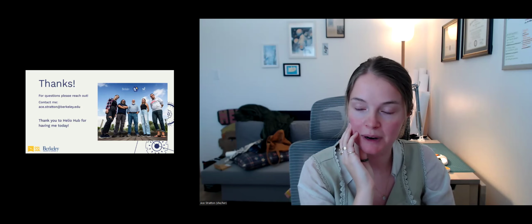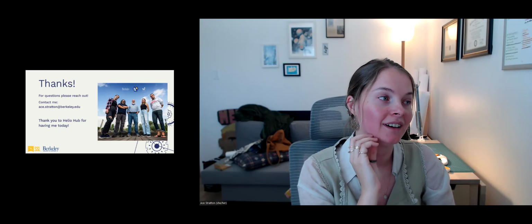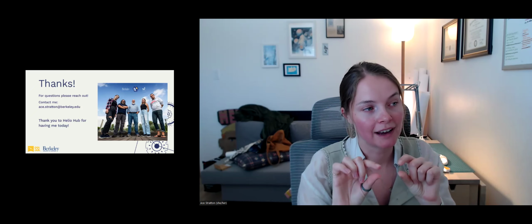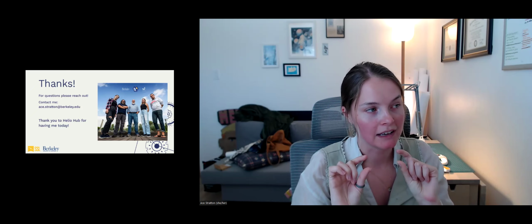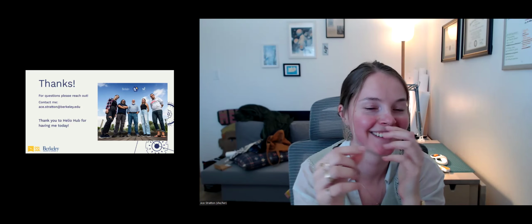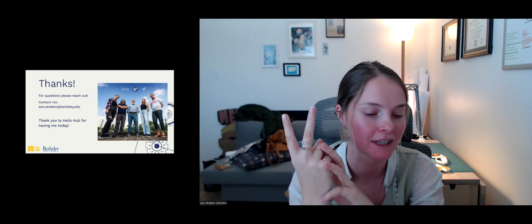So for everyone else, when you break configuration, you have to redo all of your testing to prove it's flight worthy. So we sneakily snuck out one of the counterweights and we put a second S-band transmitter in. And then we just stole the wires from inside and just bypassed our original. So we're flying with two S-band transmitters.